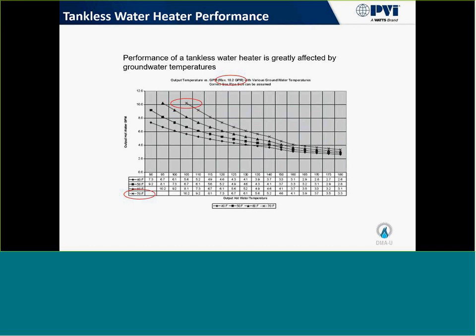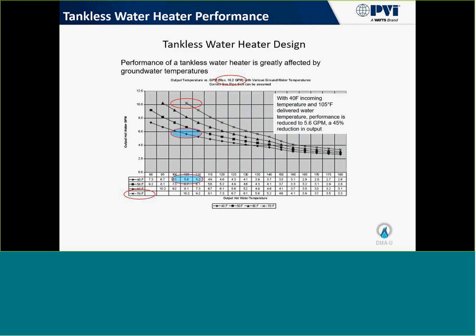So let's say it's a hotel, for instance, and you might be racking up a few of them. Your pressure loss, especially in the wintertime versus summertime, is going to be drastically different in that system. So that's also going to affect your showers. That's also going to affect things if you have thermal or thermostatic mixing valves in that system.